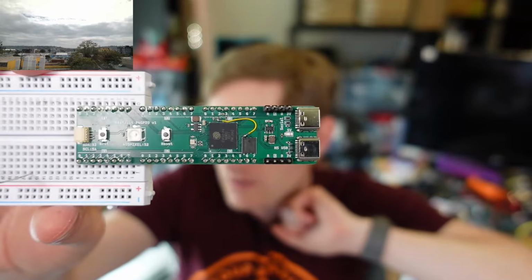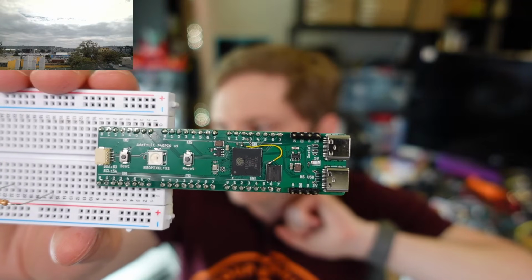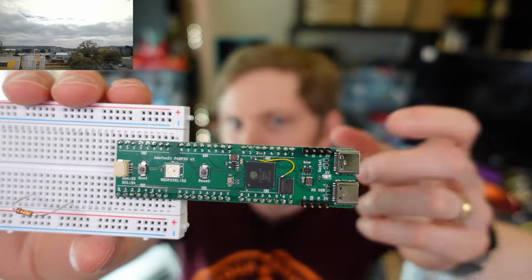This was really also a board for me to figure out all of the ESP32-P4 stuff. This is a version 1.3 of the chip. The other thing I had trouble with yesterday was that ESP-IDF 6 assumes you're doing version 3, whereas this is a version 1, so I messed that up with CircuitPython, and I had to fix that, which has been merged in. This version of the board has been merged in as well, so you can see it there.